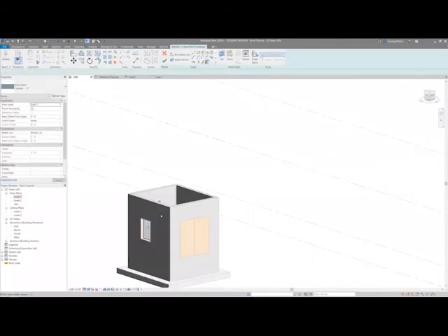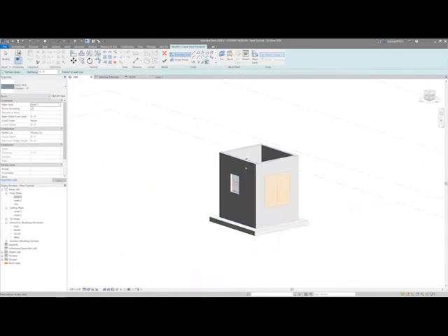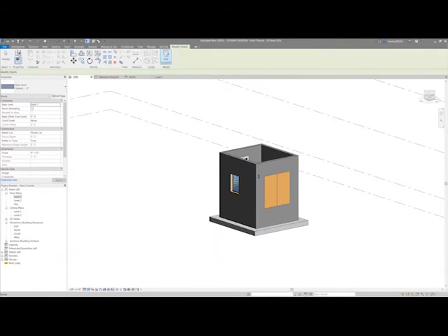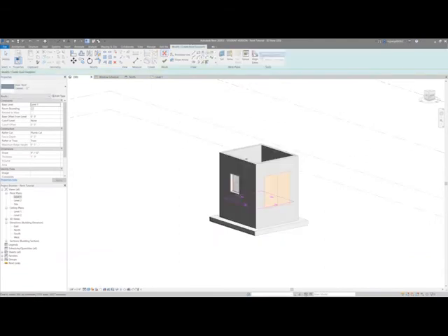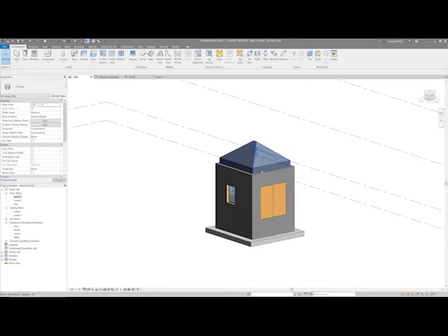And it'll literally ask you to select, just like this footing down here, just select a path to go on. You can construct a roof that way. We could say yes to that. And actually, I associated that wrong. So we say the base level of that roof will be roof, right? Actually, no, we want the base level to be the level 2 and click OK. Okay.